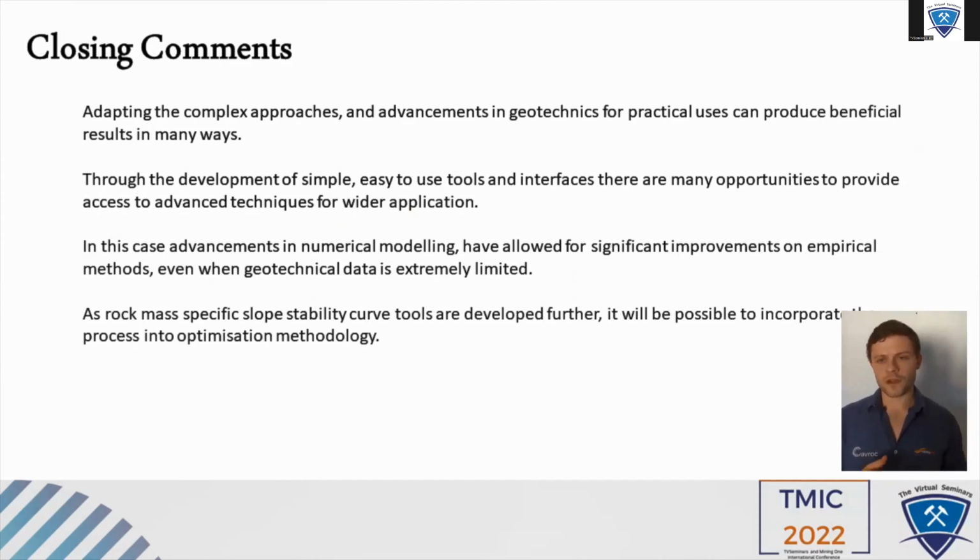I'd also say that in this case, it would be really beneficial to combine or couple the slope stability curve tools and the pit optimization tools so that they are almost seamlessly attached together. Instead of a single stable overall slope angle, you input some four or five geotechnical parameters, and the software develops those slope stability curves and runs a dynamic angle optimization based on that.